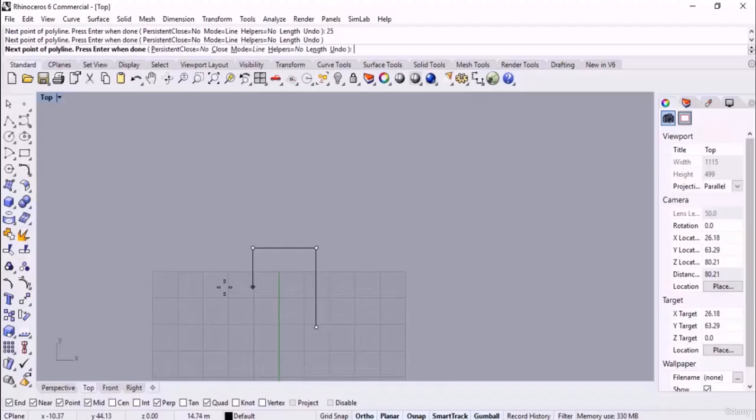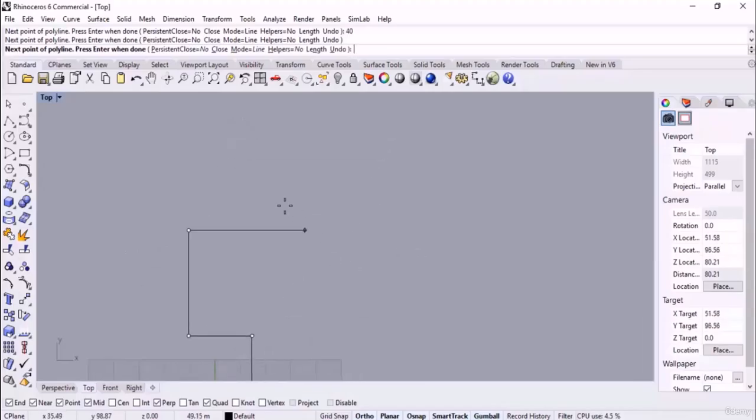As you have noticed, when you are specifying the length, we are not able to specify the direction. While in AutoCAD, when we specify the direction while entering the length, the line will be sketched. But here it is different. We sketch the line in 2 stages, specifying the length and then the direction. So this was the difference between AutoCAD and Rhino in sketching lines.